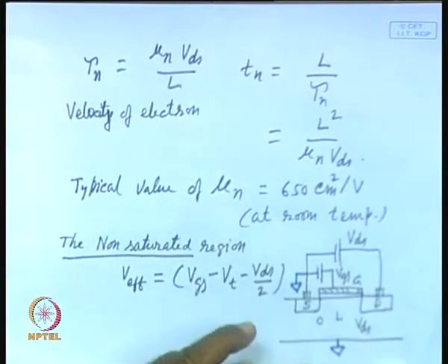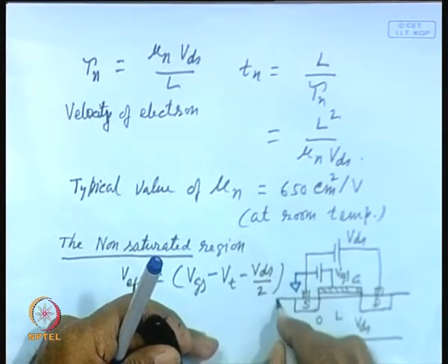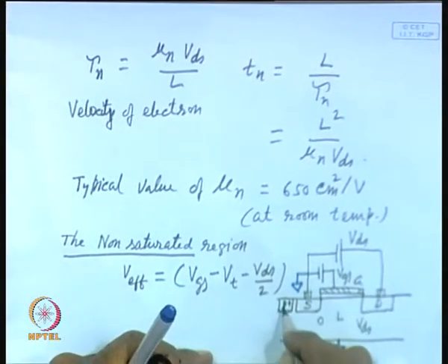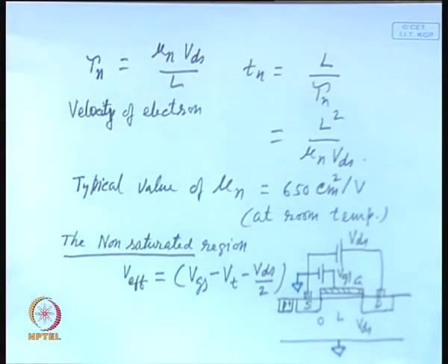And usually this is done by having a region, this is called P plus, and this P plus is actually used to connect the substrate to ground or to some other voltage. Later on we shall see how we can really apply this voltage to have different threshold voltages. So, for the time being let us assume that the source to substrate voltage is 0. Okay.